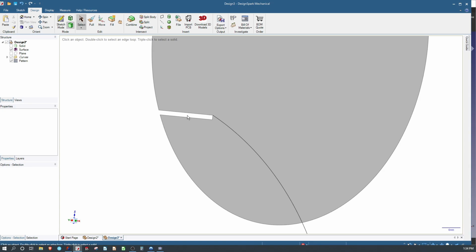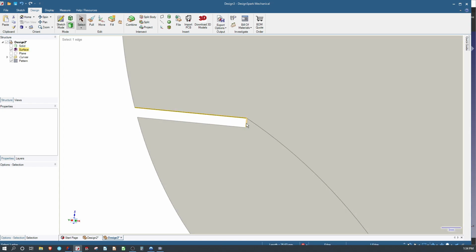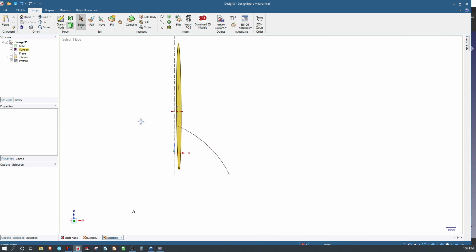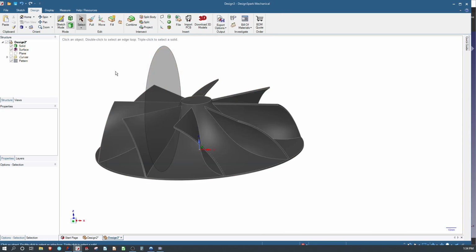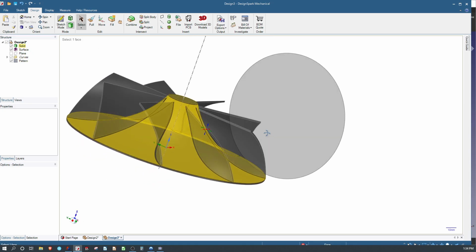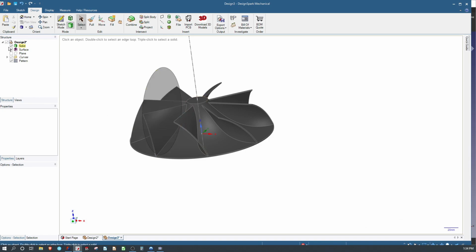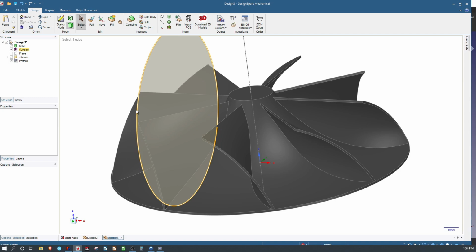So, I mean, we can edit it by saying Control-Z, but what I want to do is hold Control, select the 3 edges that I don't want there, hit Delete, and they go away, right? It updates into a circle. So that's the kind of mental thought process that you have when in a direct editor, right? You generally just keep editing what you have and don't look at the history, because you really can't without a history tree unless you hit Control-Z, which undoes all the work that you've done.